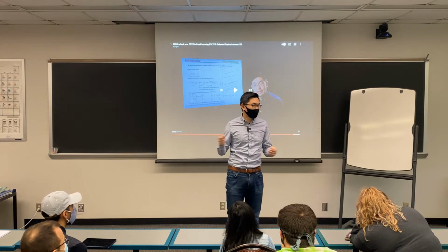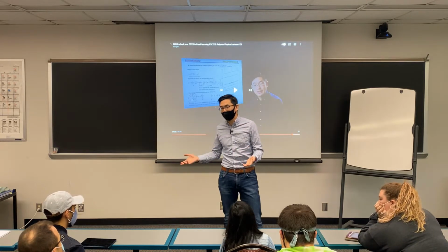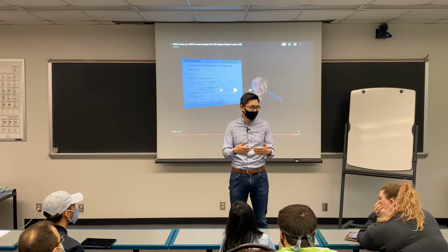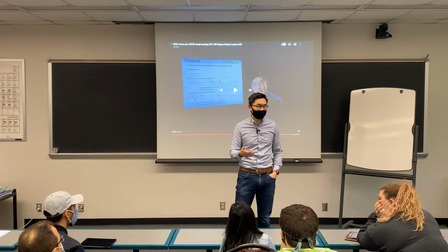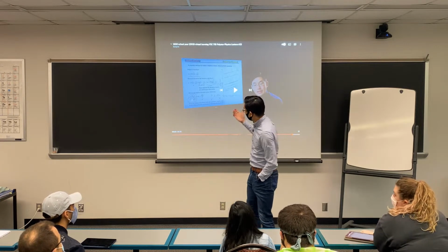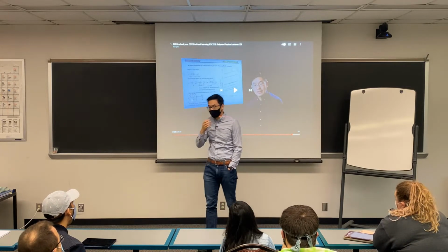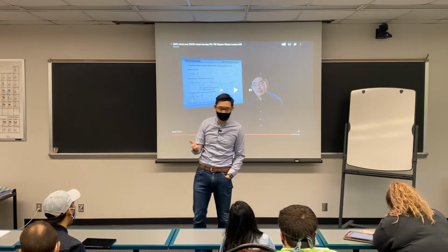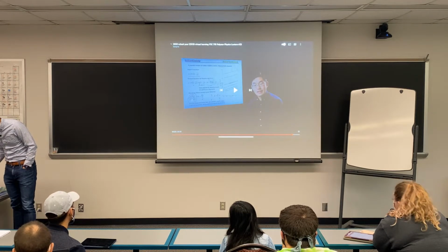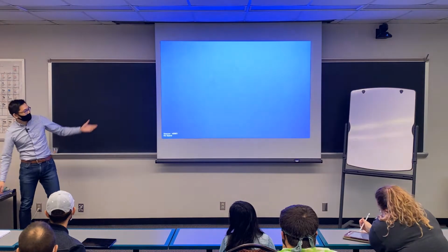This is important in many applications where you need to consider how you stretch the rubber at high extension. For example, tires. Locally, when the tire hits the ground or when you step on the gas pedal, the local strain is pretty high, and that is why it can respond to these. But at the end of the day, you need to understand a little bit what the Mooney-Rivlin equation does and how it fixes some of the early theory based on the simple Gaussian coil. Okay, so with that, I'm going to finish the discussion here.